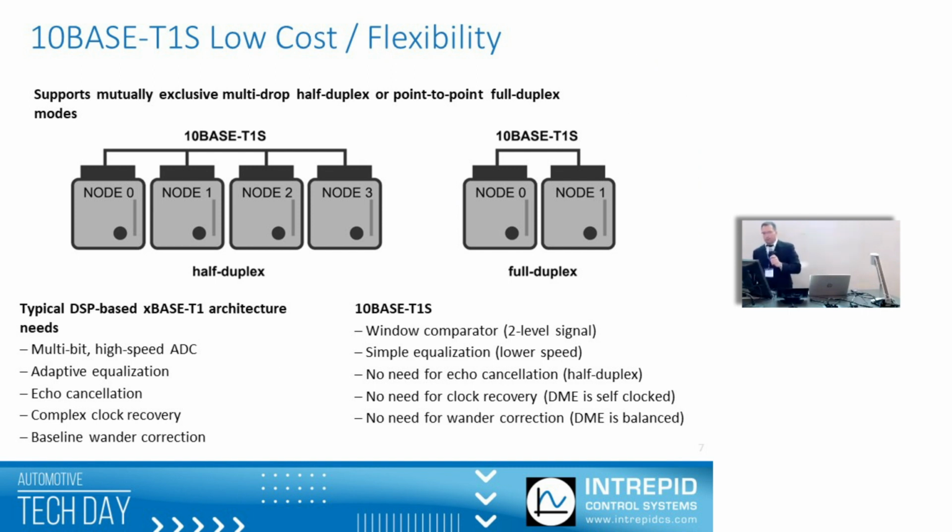So most types of automotive Ethernet, if you look at what happens, which we've done presentations on, and we do actually do training on this. But if we look at 100BASE-T1, 1000BASE-T1, multi-gig BASE-T1, first of all, the network's only point-to-point, but because we're doing higher speeds across the same copper wires, there has to be more, I'd say, DSP acrobatics that happen in order to achieve those speed grades.